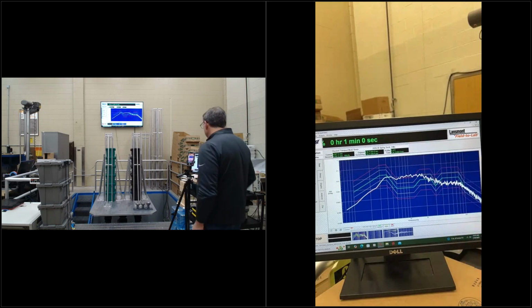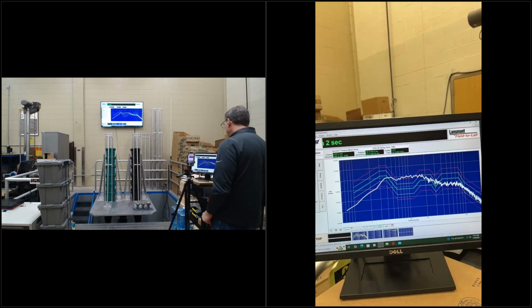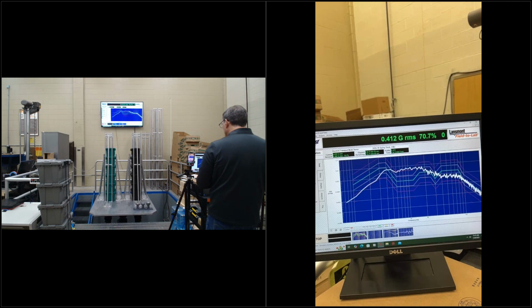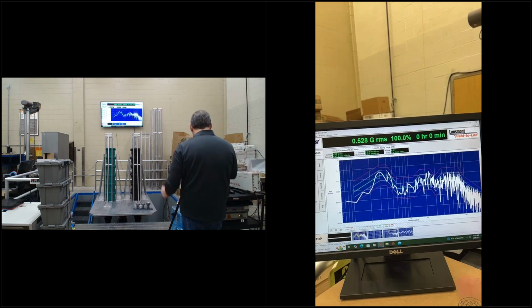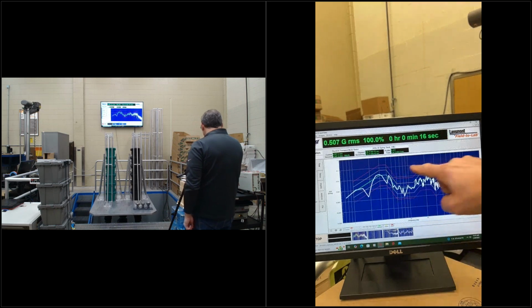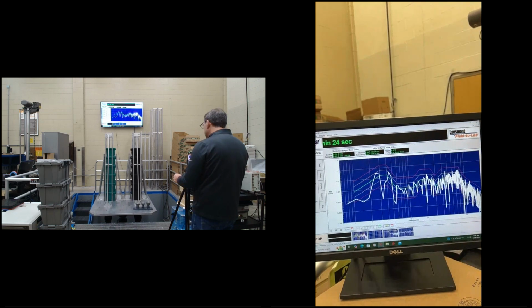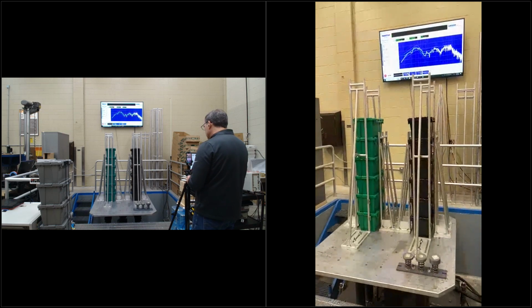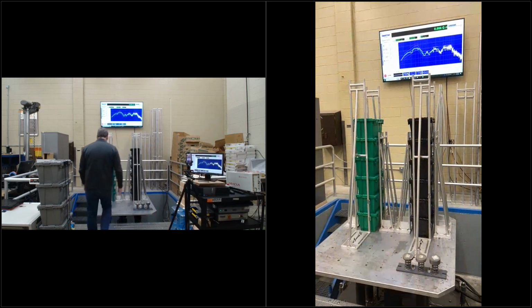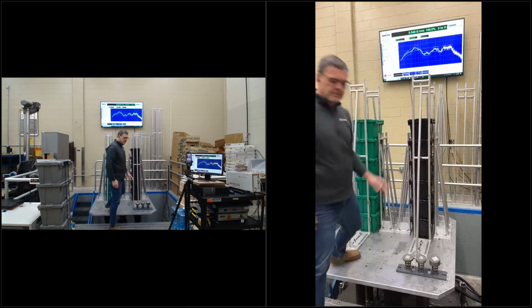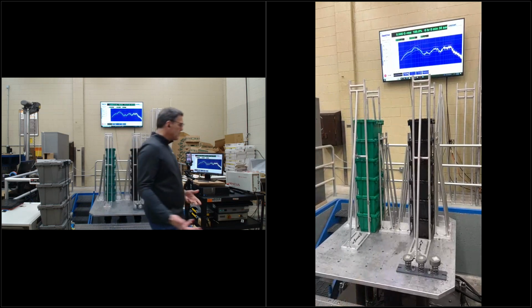Now we're switching to the newer ISTA 3H profile, the newer ASTM truck profile that has a more defined shape associated with it. Still get a little chatter, but because we don't have a flat line here in that 6 to 10 hertz range, or an area of high intensity, it actually dips down. We have less going on. We have less chatter taking place, meaning less hopping or response from either of these stacks. There's a little bit, but not much. So we're not exciting them as much.